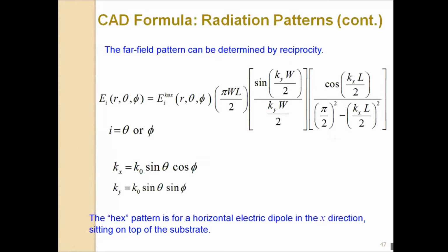For the electric field, the far field radiation pattern, if you apply it in a loop over the hemisphere, the values of r, theta, psi would come across. Theta is the elevation angle, psi is the azimuth angle. If we substitute theta from 0 to 180 degrees and psi from 0 to 360 degrees, we can construct it in a MATLAB for loop, and you can write this equation in MATLAB and vary the theta and psi values.